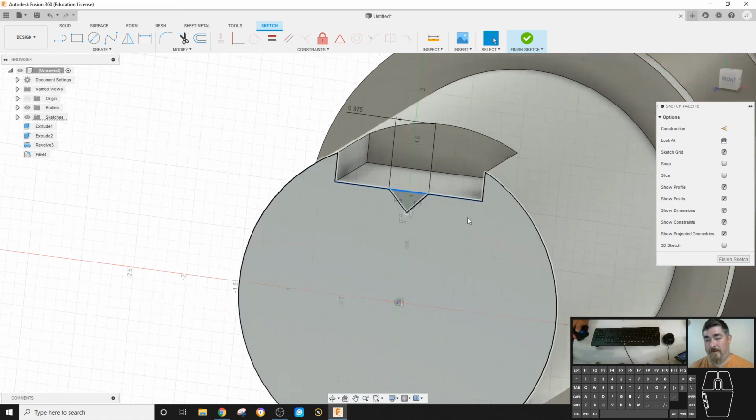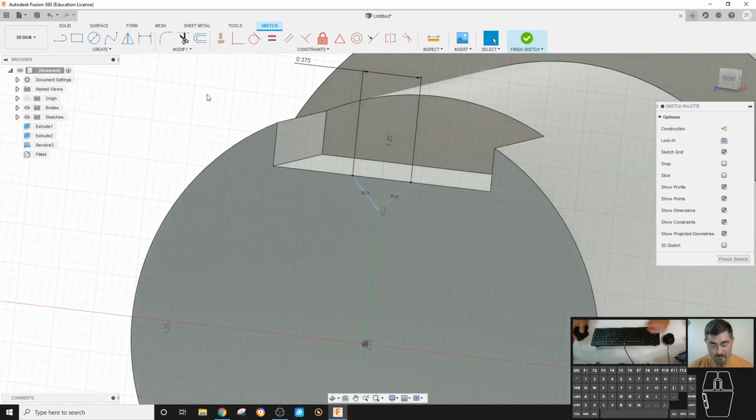Oh, now that I have this, I can show you another way of dimensioning. So if I dimension, I pick an angled line. I have the option, depending on where I move the mouse, coming straight out, aligned with that dimension. If I move the mouse over here, now I'll get the horizontal dimension. If I move the mouse up here, I'll get the vertical dimension. Okay.